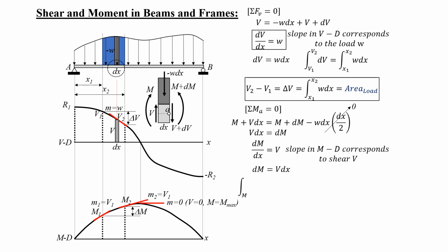So if the shear above is positive and decreasing, then you expect that the slopes of the tangents to the moment curve are also positive and decreasing, until at this point where the ordinate of the shear diagram is 0. So it is 0, and here we have negative, and the negative slope increases. So that's the interpretation.